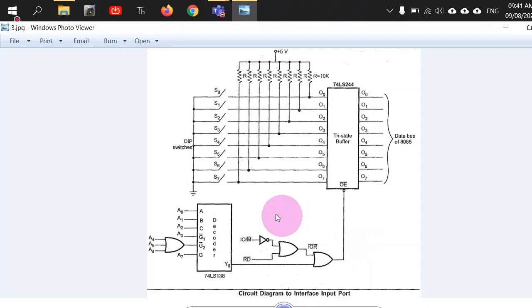See, this complete portion will vary depending upon how you want to activate. For example, if you choose an address of 55H, currently this IC is configured, since this is an input device, so this IC is configured for 80H, right? So suppose it is configured for 55H, right? And 5 in hexadecimal will mean what? 0101 for 4-bit combination. So you have this address 0101 and then 0101.